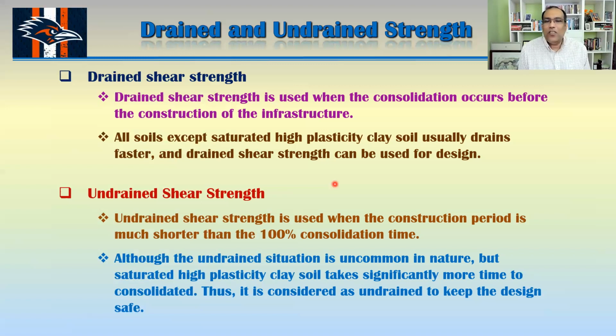And then what is undrained shear strength? Undrained shear strength is used when the construction period is much shorter than the 100% consolidation time. So basically in nature, nothing is an undrained situation. Everything will eventually drain. But how fast?